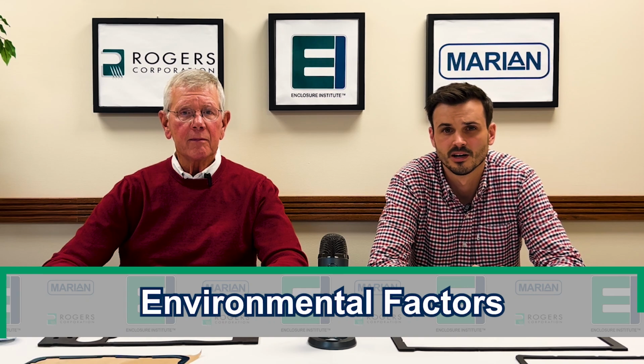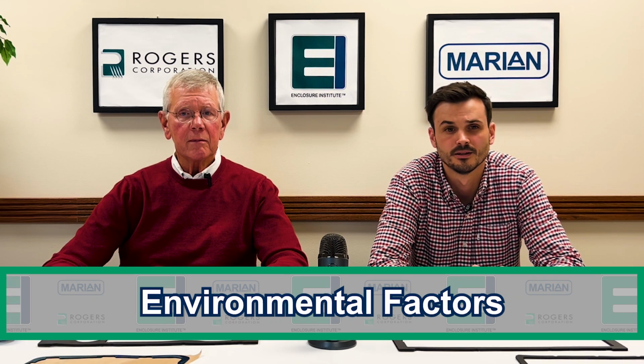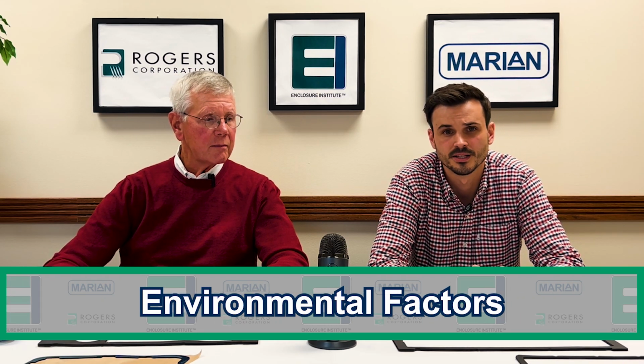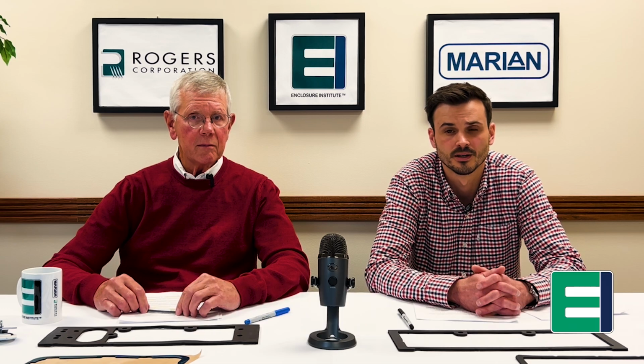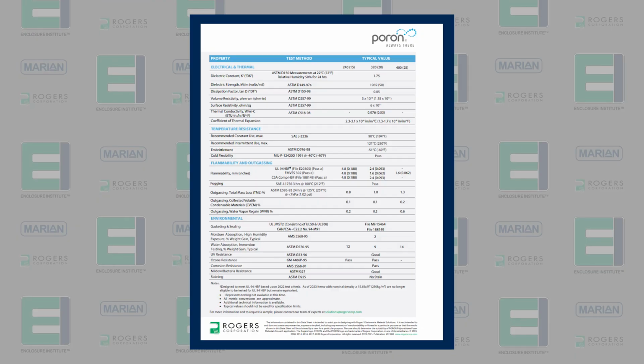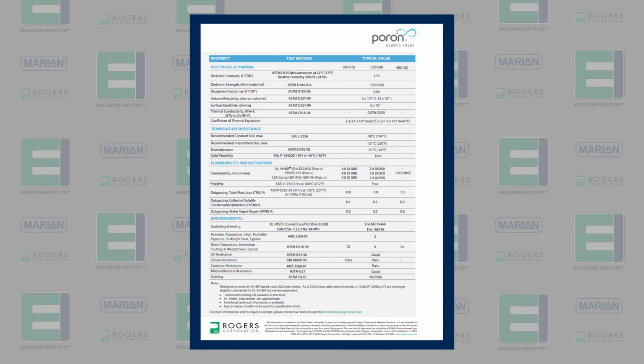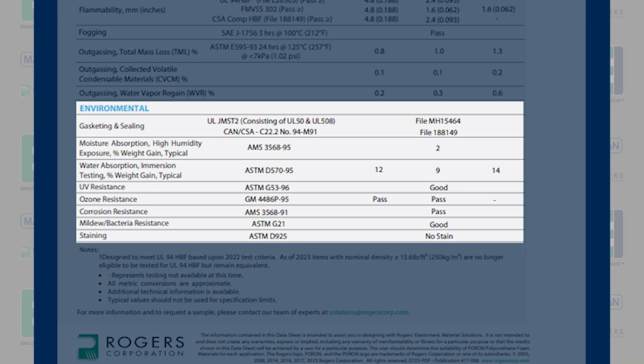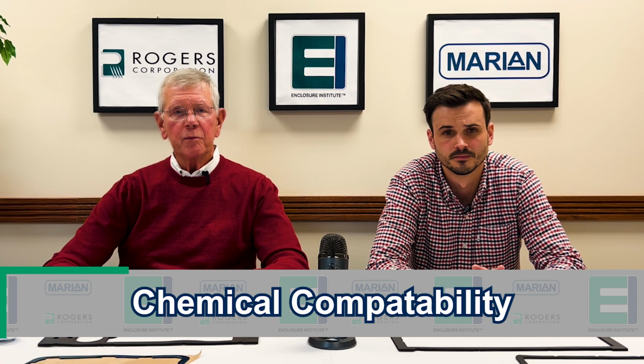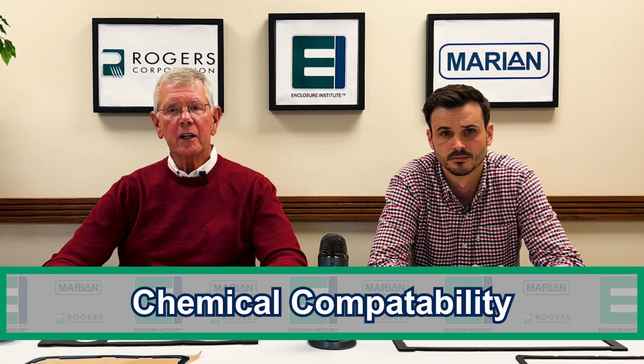Now, let's talk about environmental factors like ultraviolet and ozone. UV causes elastomeric foams to age or decompose quicker. They'll harden, crack, and become brittle. As we discussed in the previous video where we reviewed various material choices, when it comes to resisting the ill effects of UV and sunlight, a neoprene sponge can be good, EPDM and high-density urethane are better, and silicones are the best.